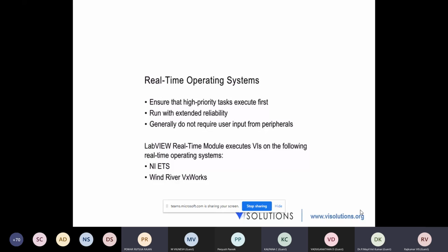Okay, it will immediately respond, because software inherently could have delays, heavy delays due to operation. So when we are going to implement an embedded system with closed loop capabilities to interact with hardware, we have to choose a real-time operating system. That's why if you see Martian rovers, NASA or whoever operates such rovers, they will have systems with a real-time operating system inside to monitor certain tasks.